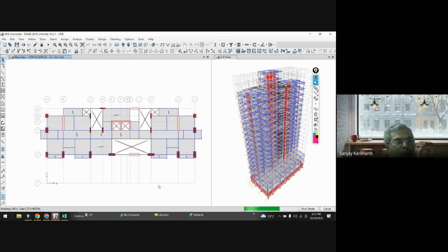Only then can any software work on it, analyze the model and get the results, and those results are again reflected on your object-based model. That is the process that is carried out while you see this green analysis. Why is it taking time? Because whatever you have given, like a column, it doesn't understand a column. So the column is converted into an analysis model made up of finite elements. Every slab is converted into finite element base.